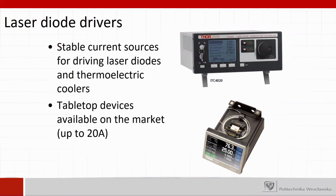So a few words about how we drive these diodes. What we basically need to operate a semiconductor laser is a stable current source, a stable current source for driving the current of the diode and also driving the current of the thermoelectric cooler if it is integrated in the laser.